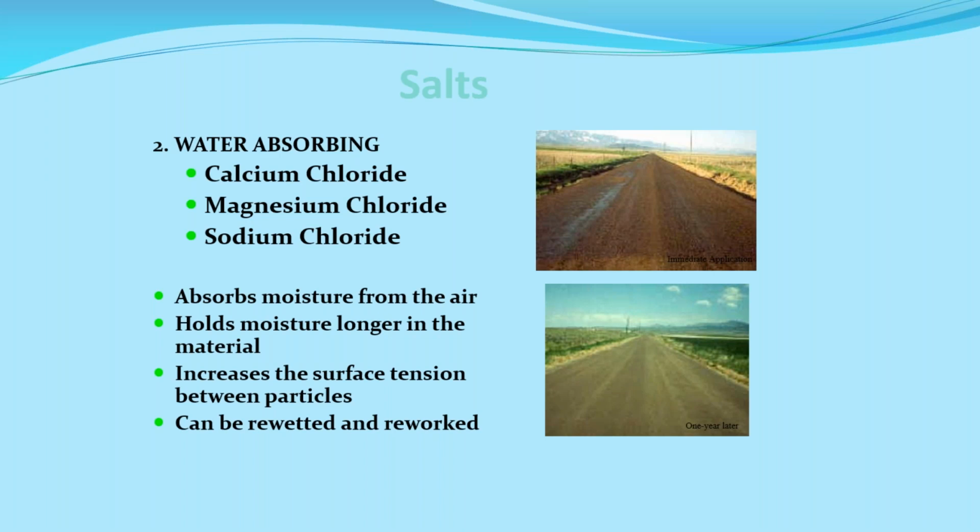Or if, say, the roadway gets pretty rough, you can come in and put some water on it, grade it, lay it back down and compact it, and it'll go back to being pretty solid. In some real dry climates, you will actually see some issues with the salts breaking down a little bit. In those situations, I tell agencies, just take a water truck, drive it as fast as you can down the roadway and spray a light coat of water on that material, and it'll come right back and rejuvenate it. So, those types of products work out pretty well.